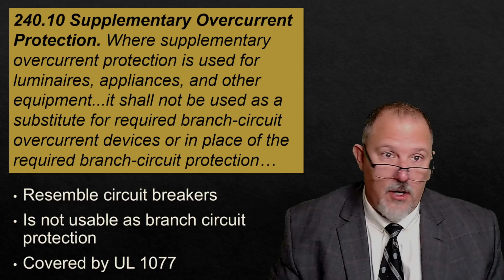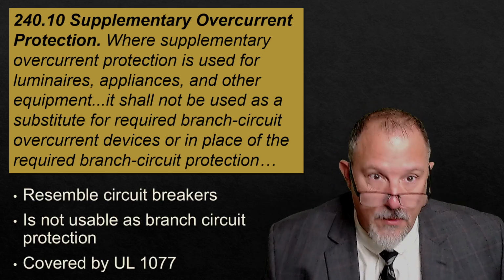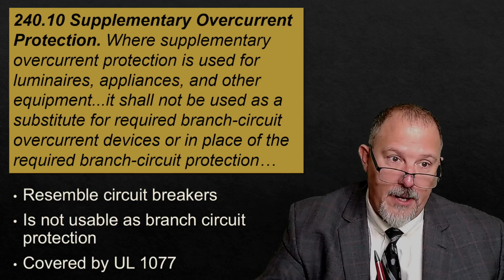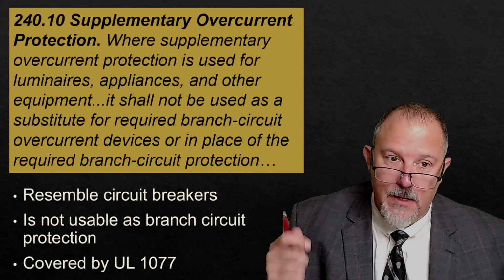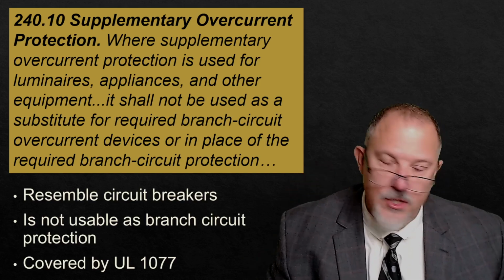These devices aren't the same as a molded case circuit breaker, insulated case circuit breaker, or power circuit breaker. They are supplementary. They're not listed. They're listed to UL 1077. It's not a 489 device. They are not suitable for branch circuit protection.